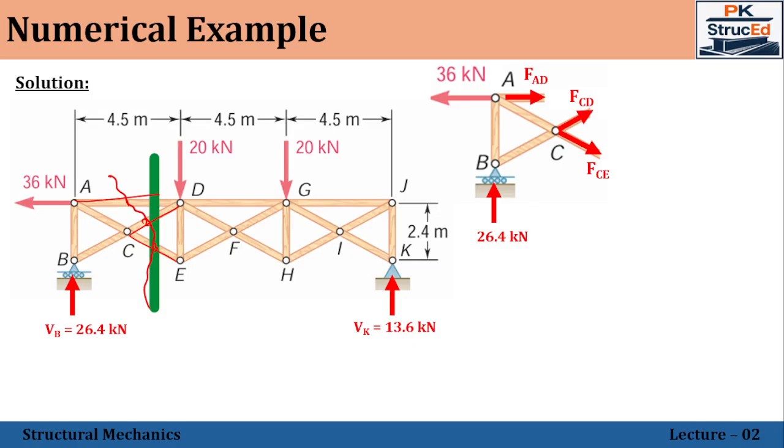Right. So next thing is that I need to apply the equilibrium equation. That is what we are supposed to do in this next case. Let me go with the moment about the point C is equal to 0. As I told, you can take moment about any of the joints, because all the joints are connected by means of frictionless pins. Pins in the sense moment is equal to 0. Why I am taking with respect to point C is that two members already act through point C. Therefore, we have only one unknown, which can be solved